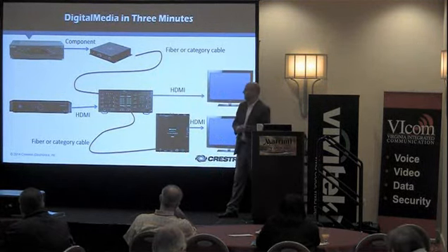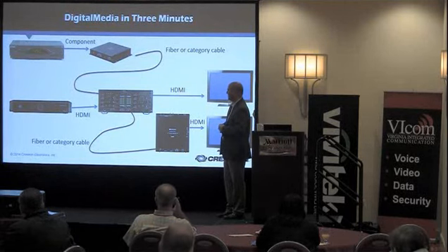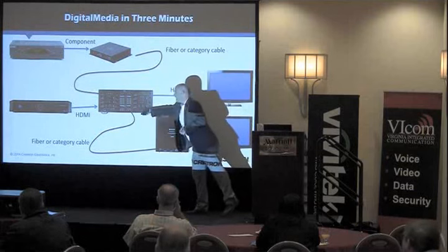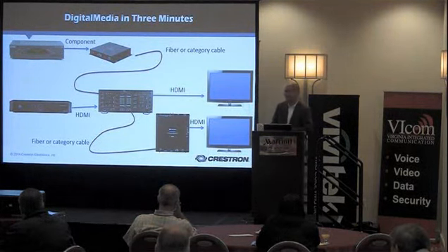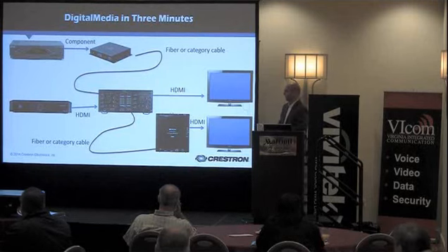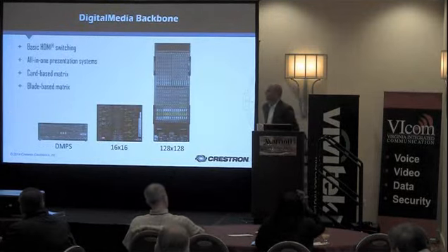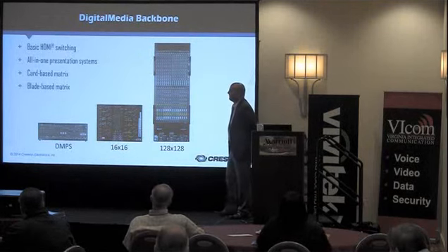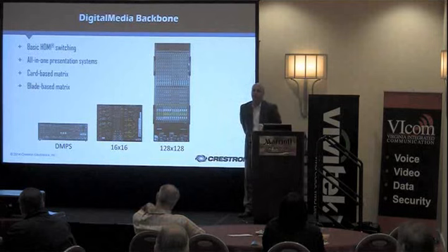All right? So getting back to my original, maybe I did take the 3 minutes. Getting back to the original idea, I'm coming out of the backplane into my receiver unit that sits at the display, and the receiver traditionally turns it into HDMI at the projector or the LCD monitor. All right? Pretty basic, right? From a digital media standpoint, we've got everything from a 2x1 switch all the way up to a 128 by 128.